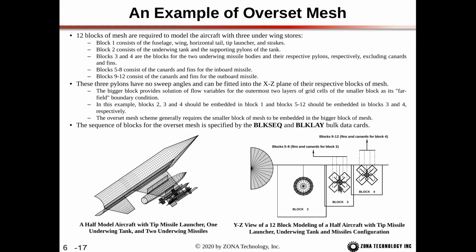So in the same situation here, where we have blocks 5 through 8 overlapping just a little bit, this overlap is not bigger than 2 cells. So that's the key point. Don't overlap these adjacent blocks by more than 2 cells.